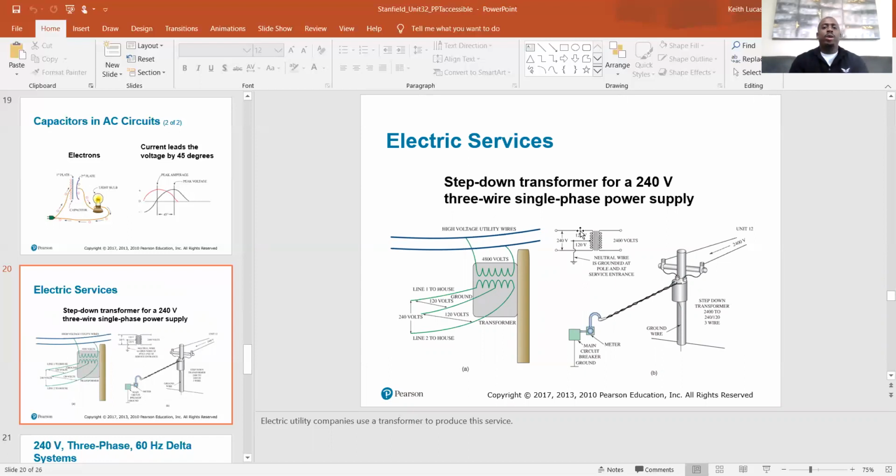But where does that come into play in air conditioning? Every system has a transformer. You got a lot of things using power in your system. So let's take your 3 motors, for example. You got your blower motor or your circulator motor, whichever one you want to call it, your indoor motor, the one that provides the air. When you put your hand in front of the vent and you feel airflow, that's because of your blower motor turning. That's a 120 volt motor.